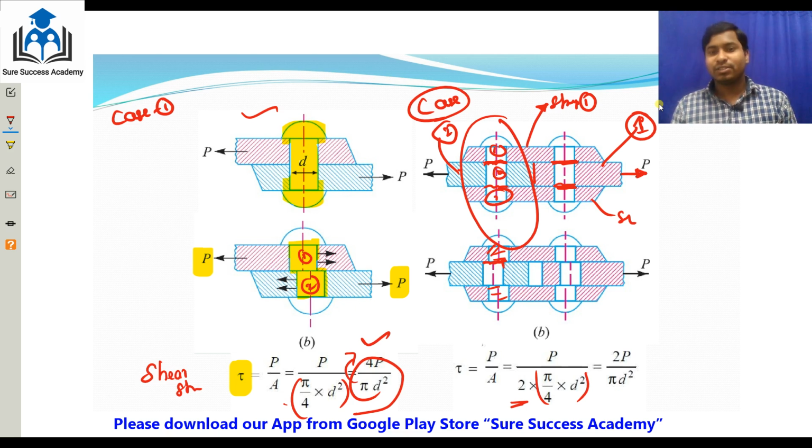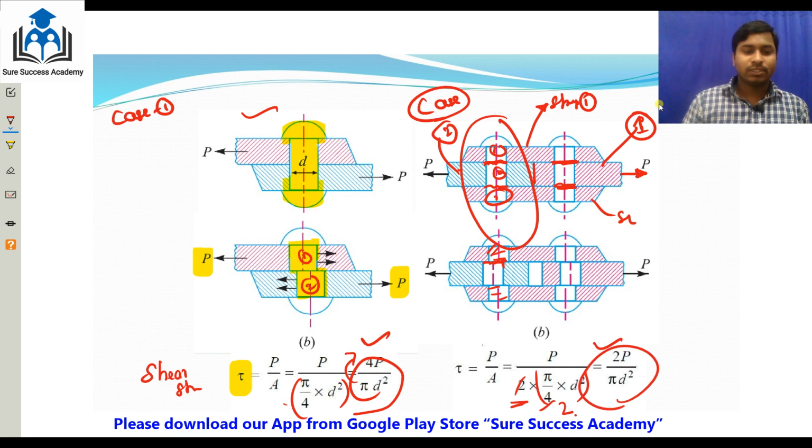Here the shear force is acting tangentially, and two cross-sectional areas come into the picture. That's why it is two times the cross-sectional area. So the 2 cancels and the shear stress is 2P by π/4 d², which is 4P by π d² divided by two. The shear stress developed here is half of the single shear.